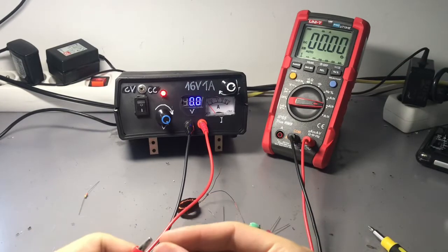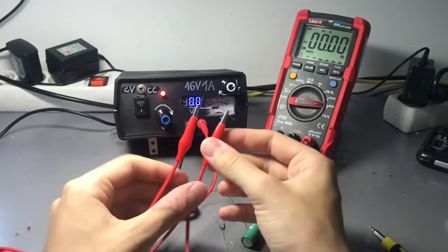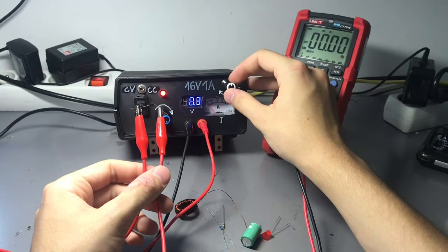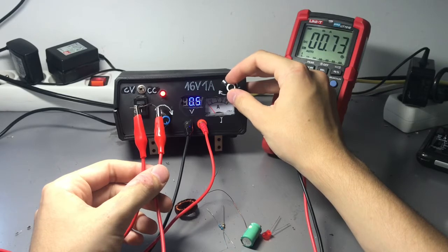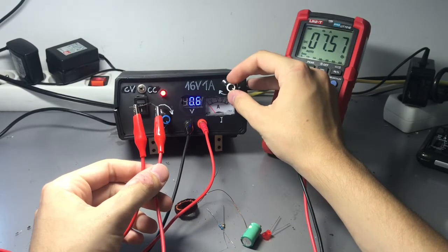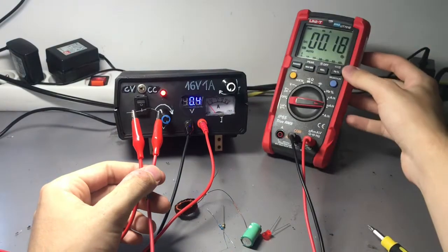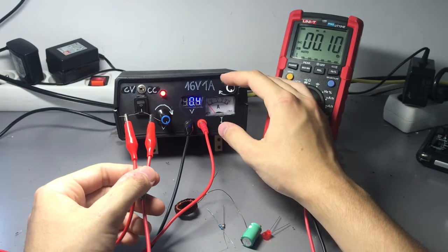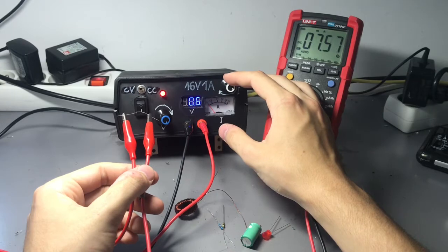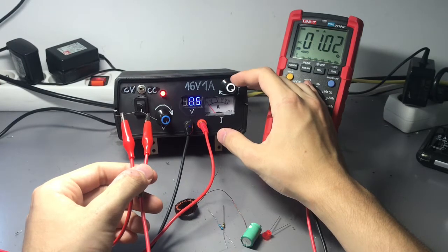Okay. So right now I connect the diode, I'm sorry, silicon diode, and right now we can see, when I start to bump up the voltage, that the current is nothing on 0.4 volts, at 0.5 it's still nothing, and at 0.6 you can see that there is this threshold and it starts to conduct some current.